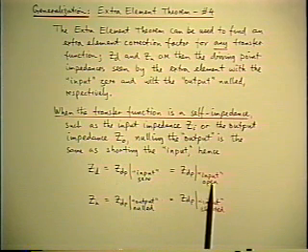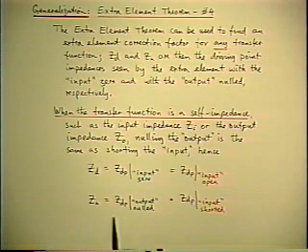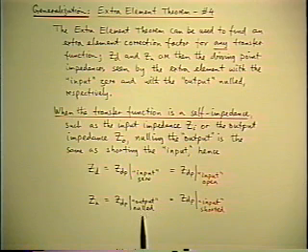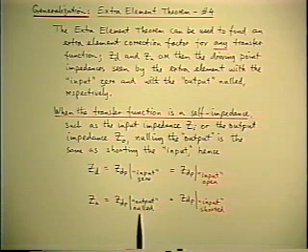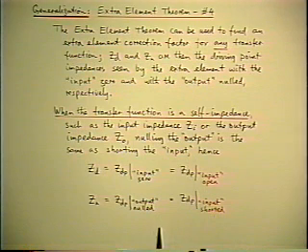That's the same thing as 0 current. And the shortcut for the calculation of Zn is that the Zn is calculated under null double injection conditions when the output is nulled, but when the transfer function is a self-impedance, the output is the voltage which is right across the input current, and therefore the output nulled condition is equivalent to shorting the input. So in that special case of a self-impedance, you don't need to invoke the null double injection condition. You calculate Zn as though it were a single injection calculation with the input shorted. And we did an example of that.